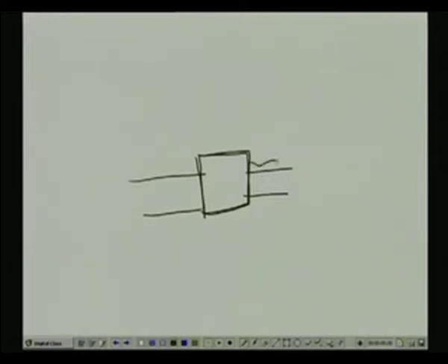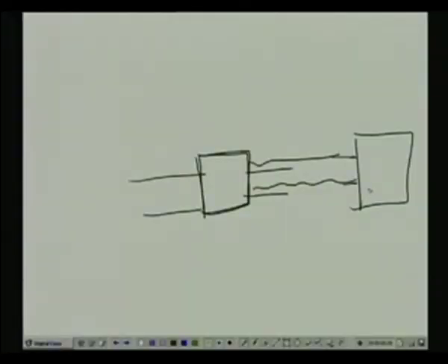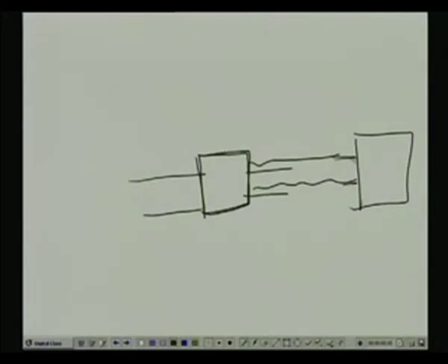These vibrations will be transmitted through a medium. Now, if I put another receiver on the other side, it will also vibrate with the same frequency, because there is a movement of the particles of the medium. This is the indirect way: I am applying a voltage, getting a force, and now the force is imposed on the receiver crystal, and I am getting an output voltage. This is the basic principle of the ultrasonic transmitters and receivers.